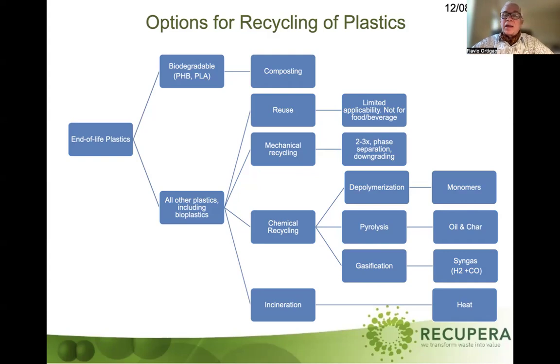You have the technology, you can depolymerize the materials, but this is also very limited. It's under development. There are certain polymers, especially when they are very clean, polycondensation polymers like PET, where it's possible to depolymerize: you break them and obtain the monomers. And the monomers are the units you can repolymerize to produce the plastics. So when you can do this, depolymerization and production of monomer, that's a very good option. And this is a technology that in many cases is already being used in bottle-to-bottle recycling.